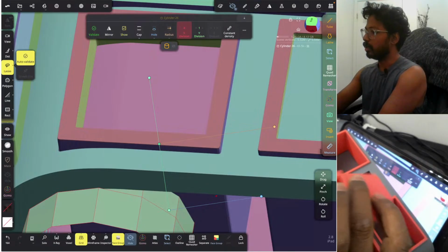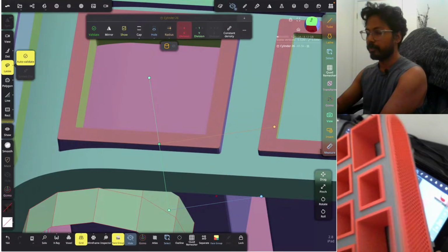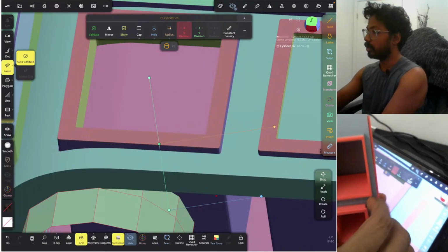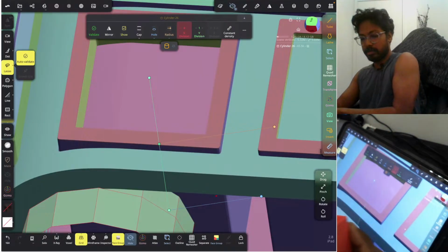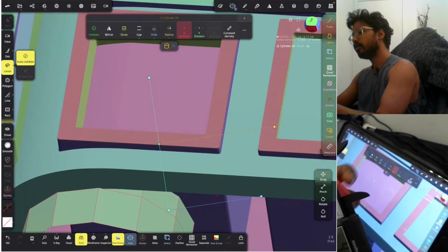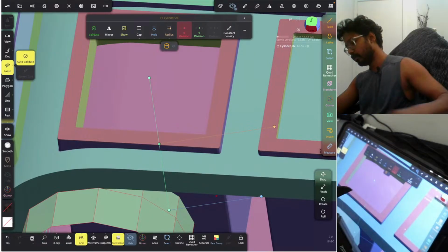We just need to insert it. It just goes in smooth, and that's how I gave the tolerance there. Let me measure it. So for the width, it was 30 mm, 30.5. That's what we have here.